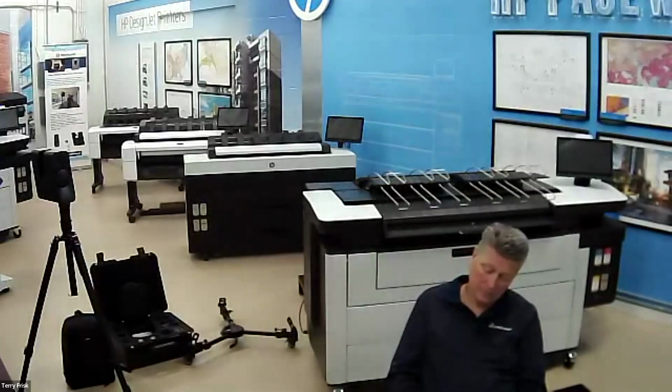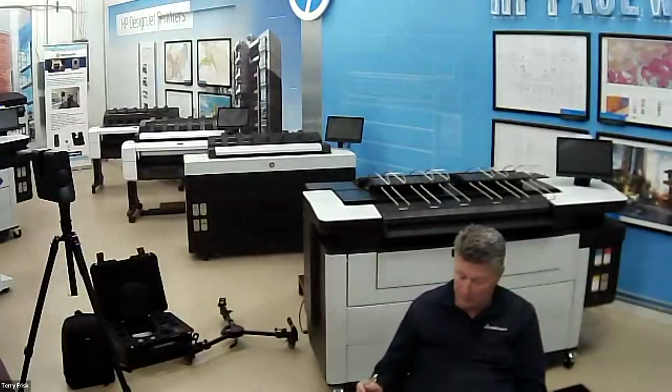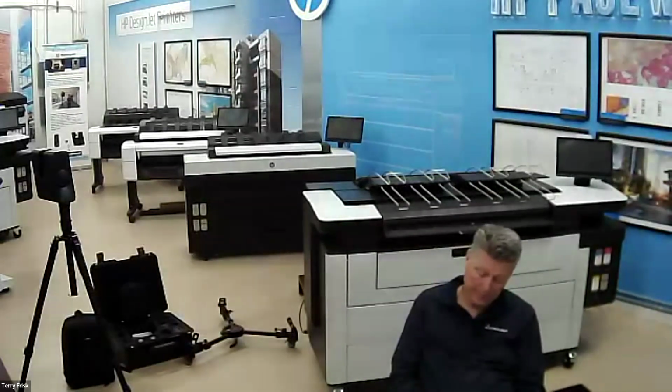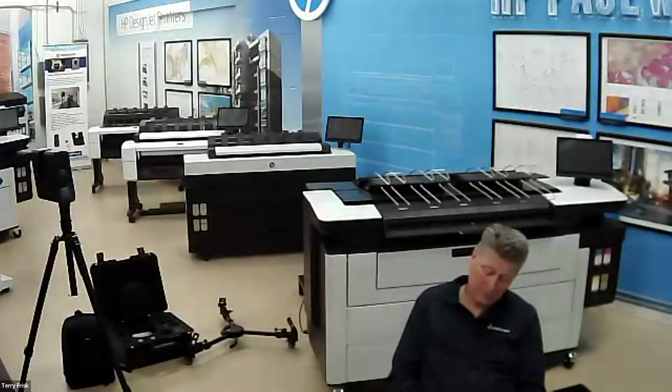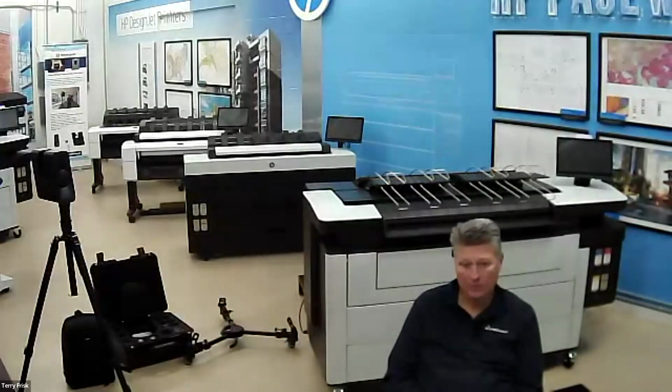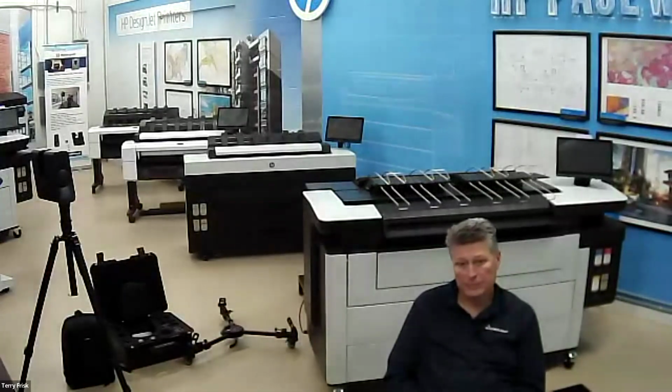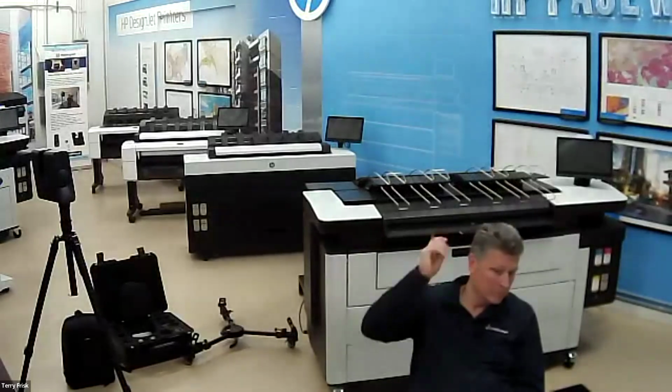If you're scanning a big warehouse where there's nothing inside, you're going to be able to go very quickly, moving the scan points every 6 feet, through the entire space. However, if you're scanning, for example, a big hotel with lots of walls and furniture, you're going to need to move around the space. So it depends on a few factors, but generally in a dense space, we say 30 minutes for 1,000 square feet.